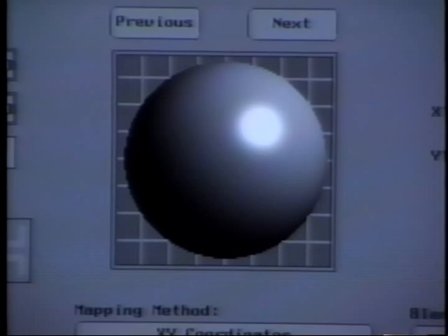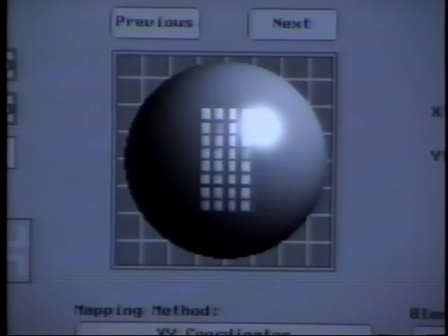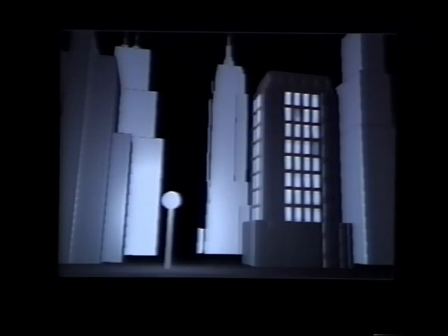Some programs separately label this kind of mapping as luminosity or incandescence mapping. Now the value of the ambient slider, which is being multiplied by the scene's global ambience setting, determines how much the map adds to the illumination of the building. The black pixels of the map don't add anything to the illumination of the surface, so they effectively mask themselves out. If we preview, we can see that the windows are self-illuminating, but the sides of the building are still shaded by the light from the lamp.